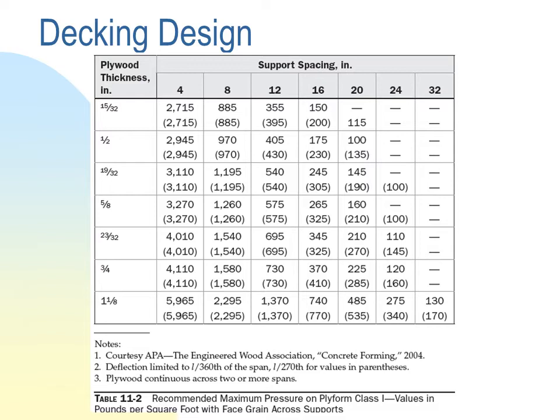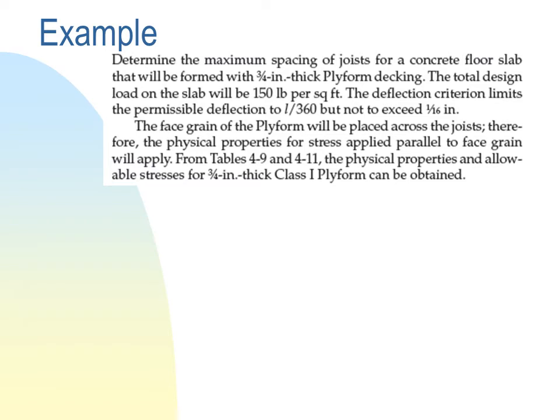So you should be very careful. And again, there is something very important to know here. That table does not include the absolute deflection criteria. So this table summarizes 3 equations. But the 4th equation for the absolute deflection, which is actually 1/16 of an inch, is not included in such a table. So let's take a nice example here.